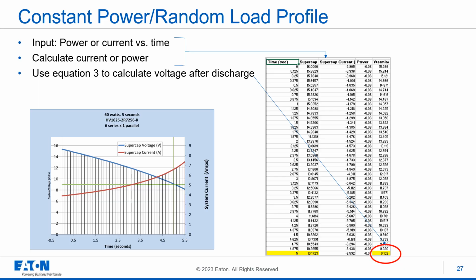The previous two methods were an example to show the calculations, but neither really calculates things properly. With method 1, we underestimated the voltage drop due to ESR since we used the average current. This underestimates the total voltage drop and therefore underestimates how much capacitance will be needed. With method 2, we did not take into account the voltage drop due to ESR at all, so again, the capacitance is undersized.